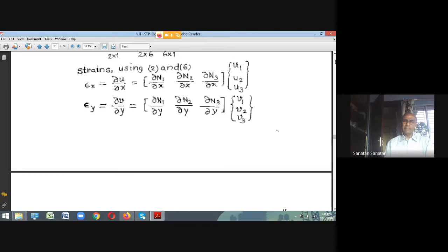And it's a function of x and y. But suppose you think of it as a rectangular plate and then you break it into a number of small triangles. If you look at the surface just above that small triangle, that portion of the surface will be like a small curved surface. That is a doubly curved surface, a function of x and y. But if you want to approximate it by a plane surface, it will look like a triangular tile.